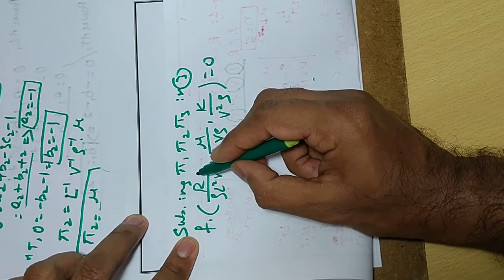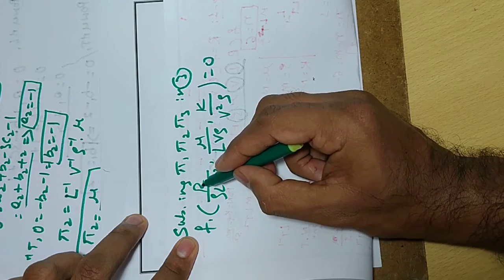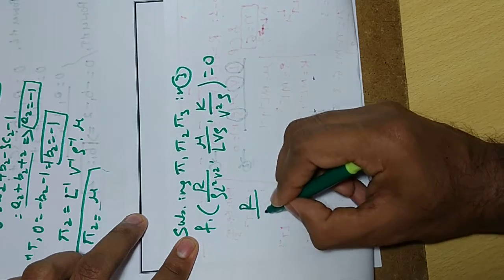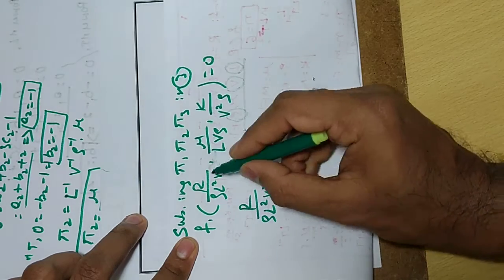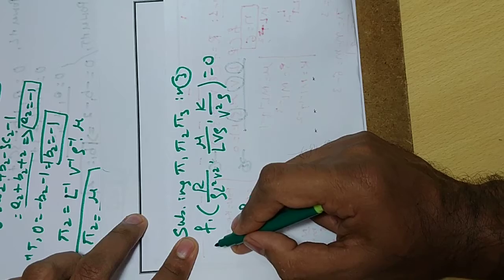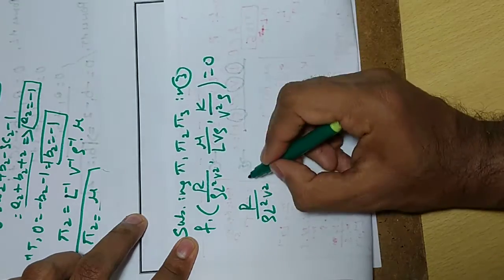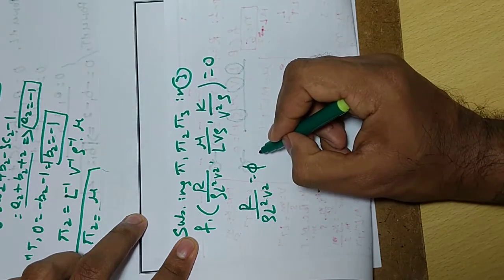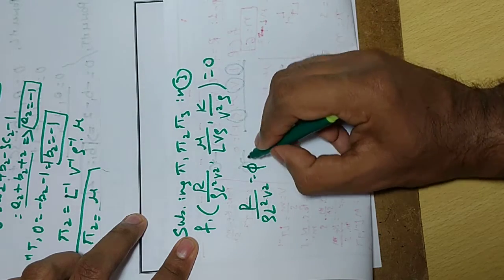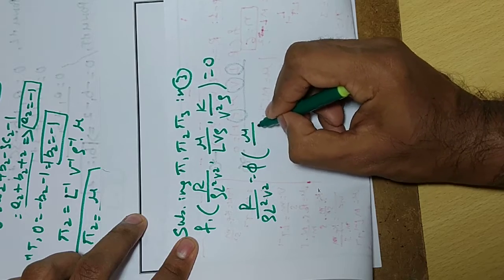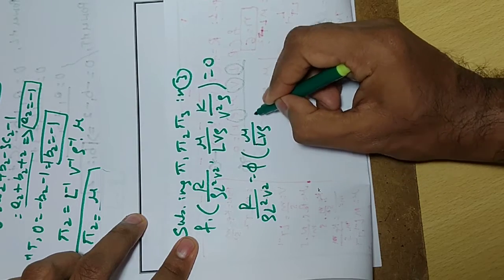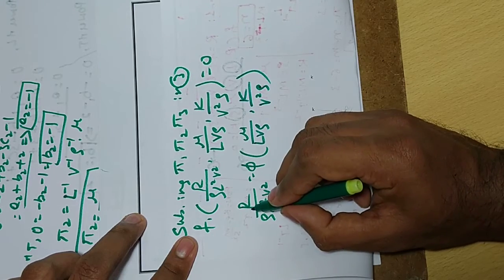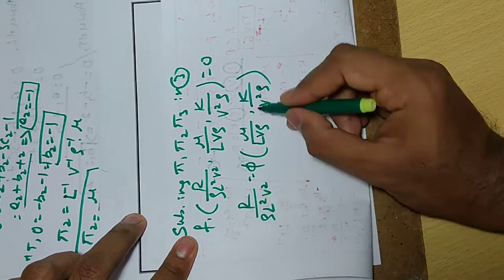Actually, in the problem they ask to relate this dependent variable with respect to the other things. So you take r by rho L square V square in the left hand side, and you take all the other things from the function to the right hand side. You have to write one dimensionless constant term, pi of mu by L V rho comma k by V square rho, because in the problem they tell to relate this r with the other terms.